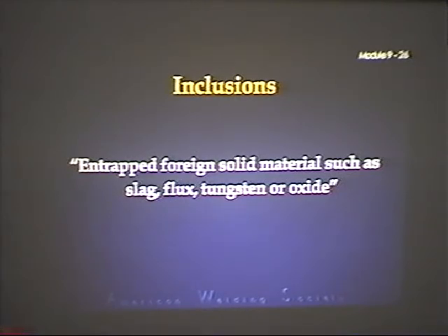A lot of times if you're using a cheap steel, there'll be slag left in that steel from the refining process. It actually lays in there as a lamination, and you're welding away, and you could suck it into the weld. So you get a discontinuity like that. That's why if you're working to code, you always have to get an MTR, a mill test report, to make sure that the metal that you're using meets quality control standards.